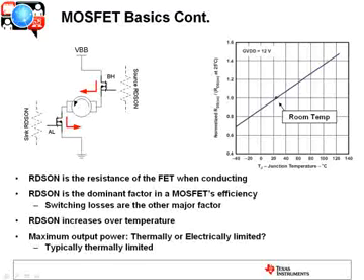So one of the keys to good motor driver design is how do you thermally handle that device? Can you efficiently get the heat out of the device? If you can guarantee you can support the continuous current ratings, and depending upon the device, you may even be able to get higher current ratings out of that device if you can thermally get the heat out of it. That's not the case for every device, but many devices are thermally limited. The challenge is how to get the heat out of it to ensure that you can keep maximum current flowing out of the device.